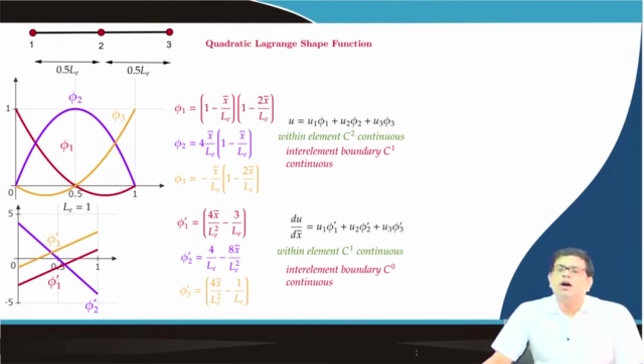So there it may so happen that in some portion of the domain we encounter a constant deformation field or constant axial displacement. So the interpolation property, that is summation of phi_i(x) equals 1, is just to represent that constant term, so that our approximation is able to predict the constant term.